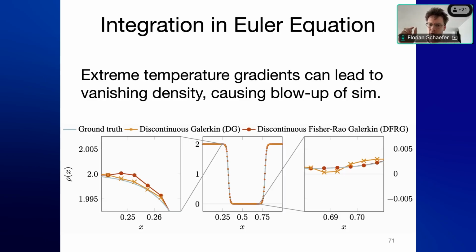Whereas if your density goes to zero, your wave speeds blow up. So I'm starting to wonder how many times when I see negative pressure, it really comes from the density first becoming very small, leading to a blow-up of the equation that you then see in the negative pressure. The first thing that went wrong was the small densities, which mean your wave speeds blow up and then your simulation blows up.